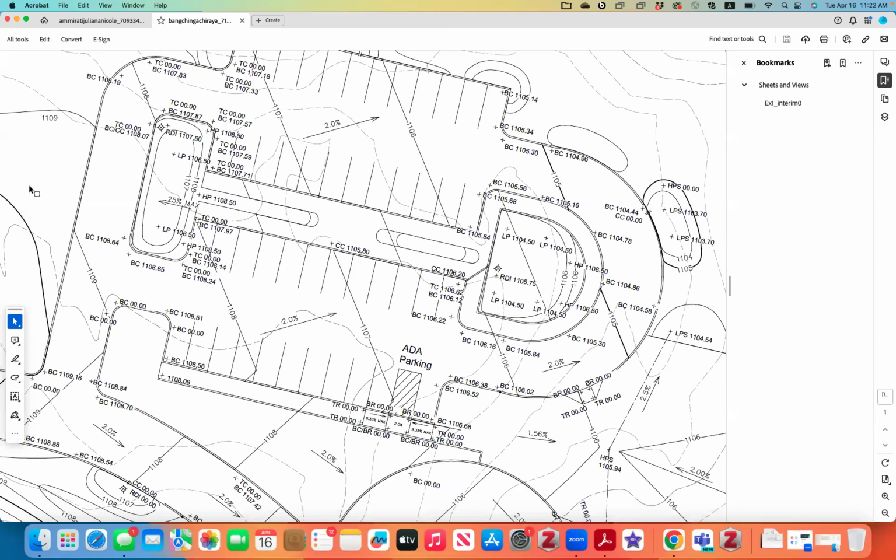Yeah, they're the bottom of the curb and should be based on the parking lot contours. Right, and then the BC and the TC you just add 0.5. So you're saying bottom curb and curb cut are the same? Yes, when you have a curb cut, you would say CC/TC. You do not need another BC because you don't have a curb there.